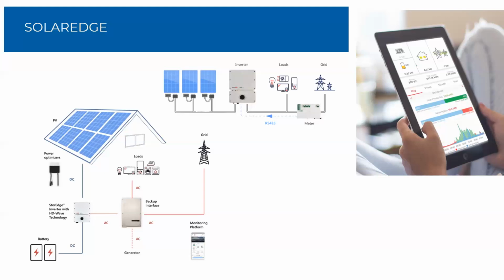So that when I'm ready, all I have to do is slap on a backup interface and the SolarEdge battery, and that's the only addition I have to make. So you're making less of an investment later down the line by adding the backup interface and the battery than you are with installing a whole additional battery-based inverter.